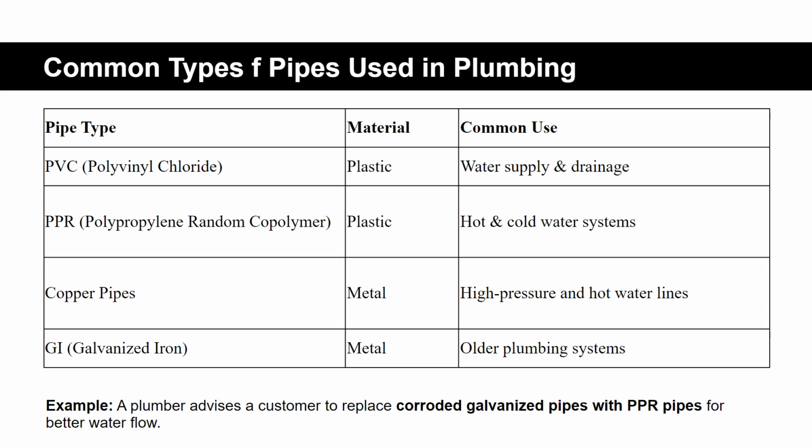Maintenance isn't just something you do when there's a problem. There are different types of maintenance, and each one plays a role in keeping the plumbing system strong. Preventive maintenance. This is the routine work you do before anything breaks. Checking for wear, tightening joints, flushing lines, testing valves. It's the best kind of maintenance, because it prevents the need for repairs.